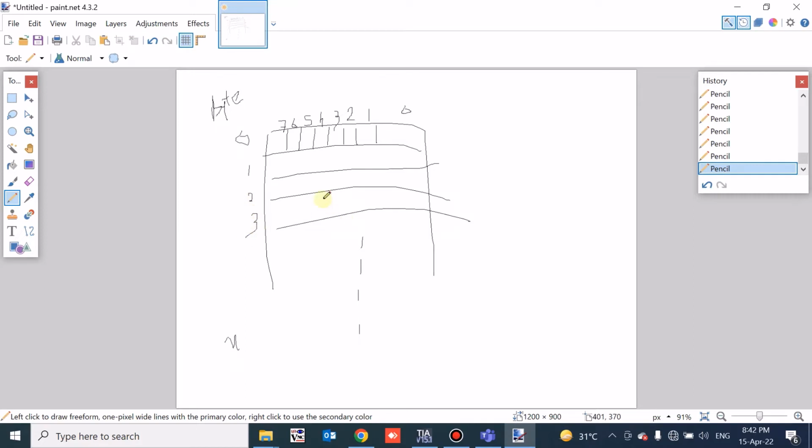So this whole addressing will be divided in bytes. The first input will start from byte 0. You can change it anywhere, like byte 1, 2, 3, but your address will start from the byte. I indicates the input address. Next is your byte number, then a point, then your bit address. So you are accessing this input, which is I 0.0 for the input.